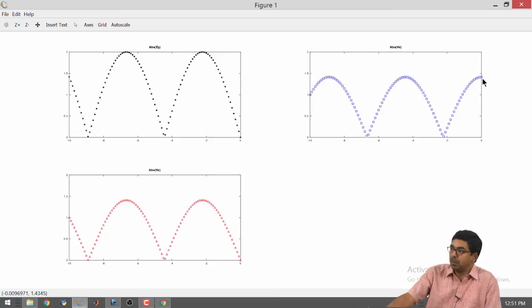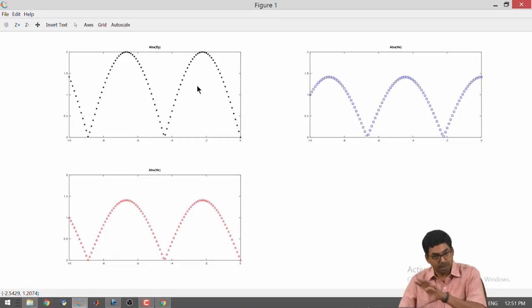We need to talk about what kind of surface currents will exist on the surface of the conductor. The summary is that in the case of a dielectric conductor interface, in the dielectric medium you will have standing wave patterns with respect to z, and with respect to x it is a travelling wave.